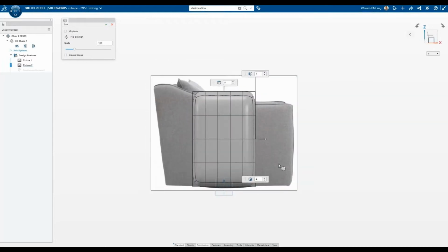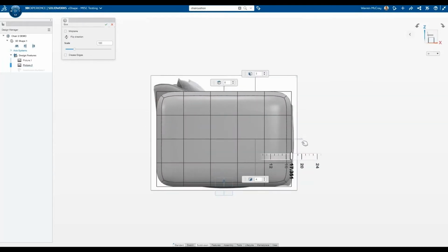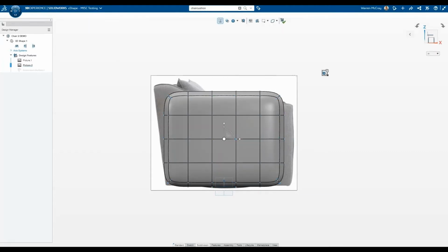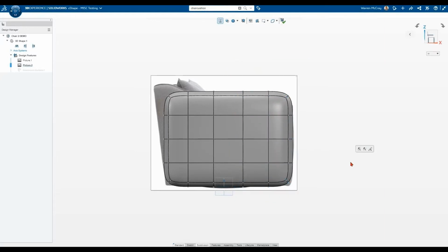I'm not trying to duplicate the chair. I'm just trying to get a feel for this design and try to come up with my own design. So what I'm doing here, I'm window selecting the vertices that are on the primitive, and I'm just grabbing them, and I can rotate. If I mouse over the graduations on the large values, it rotates, or if I zoom in or move into the smaller graduations, it snaps in place.